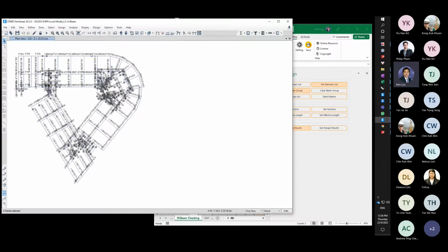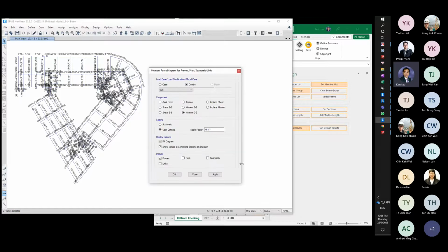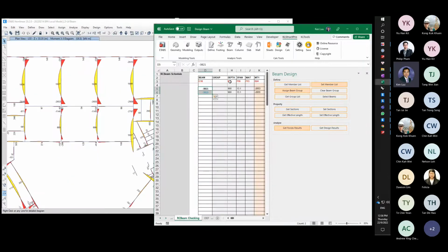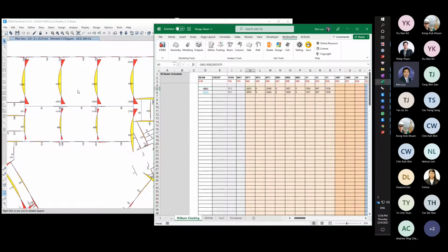So that's the way you can select many beams. And then here you can click show the moment, and you can see that it already shows the maximum moment in, let's say, this beam. It showed the maximum at this section. MT2, of course, the negative moment, you don't have anything, and MT3, yes, you have some moment here. And MB1, you also don't have anything, but MB2 is the maximum positive moment. So the V also shows you the shear at each section.